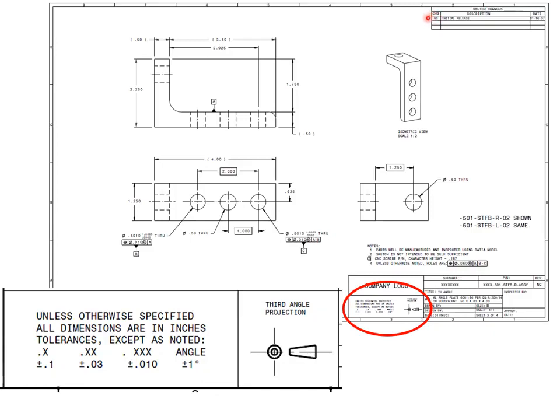Once we make a change, we would now use the alphabet and start with the letter A, and a brief description of what you changed. Diameter 0.59 changed to 0.65 diameter. Look at zone 6B. So this is letter B, this is number 6. You tell them at zone B6, look in that area, look for that dimension. So this dimension now has been increased, or the diameter has been increased. And then at the end you have the date of the change and typically the initials.